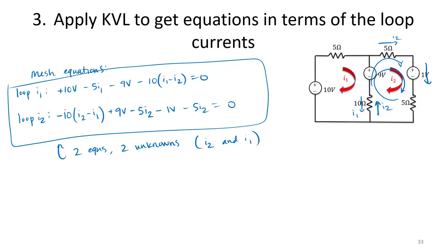One thing to be careful of is signs, so make sure that you pay attention, especially for this first resistor, you have a voltage drop, so be careful not to forget negative signs for voltage drops. And also when multiplying through, make sure you remember to distribute negative signs across all the different parts of your expression.